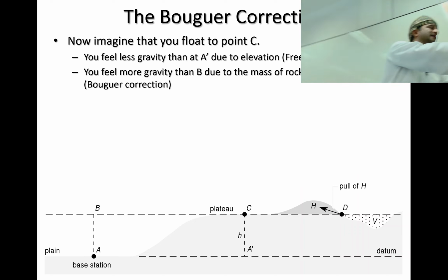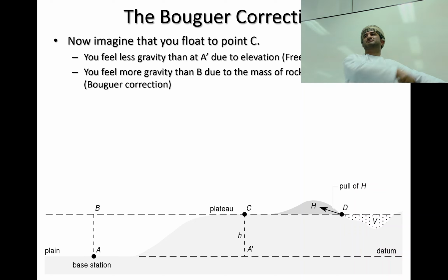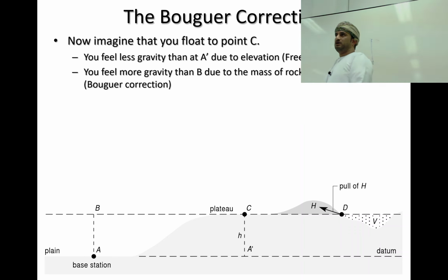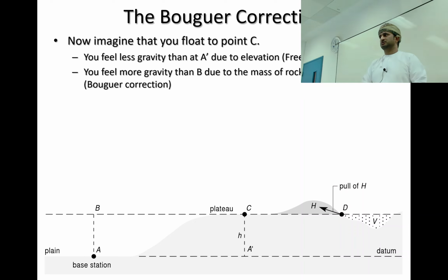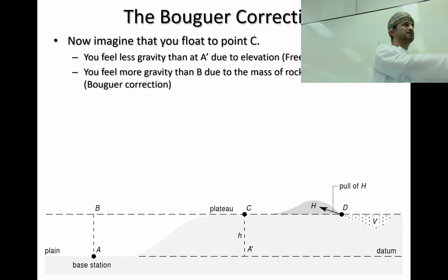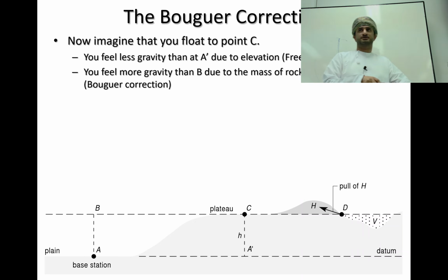You come back. After some time, you come back and take measurement here. We repeat measurements where? The reference points. That's how the drift correction is done. You return back to the base station. You keep returning back to the base stations.